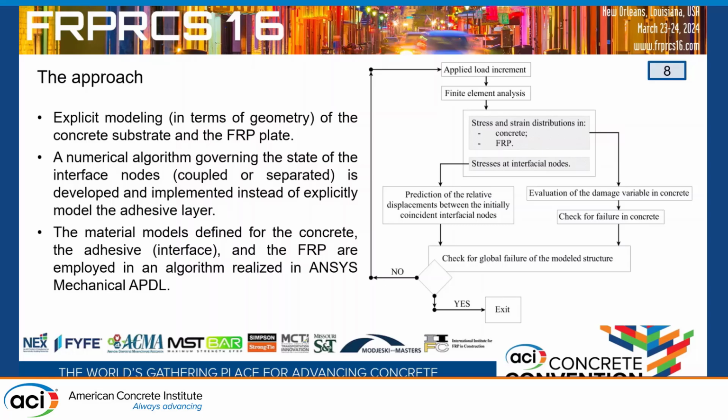The flow chart of the numerical procedure is shown on the right. So basically, we are using an incremental procedure to simulate the quasi-static loading. For each increment of the applied load, stress and strain distributions are defined throughout the constituents, and constitutive relations for concrete and for FRP are run.